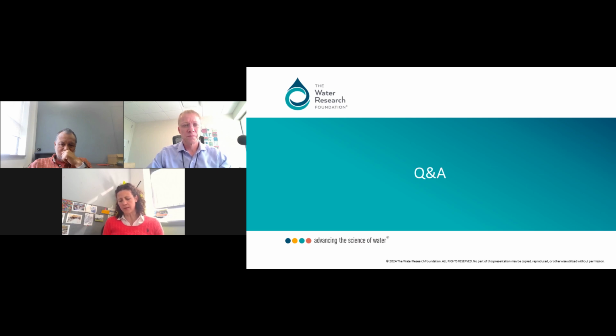We really emphasize in the sequence the relevance of good DO control, because with the advanced DO control systems we have today, it is possible to transfer facilities from high DO to low DO in a safe manner and maintain the same nitrification performance or get better. As Dan said, I agree with him that we were not worried about denitrification or phosphorus removal, because that seems to just follow suit and get better. We really focus on nitrification. And so I do emphasize how important the DO control is.